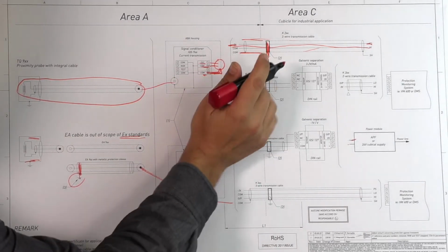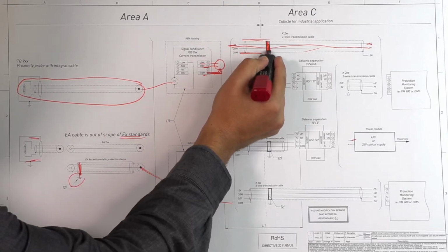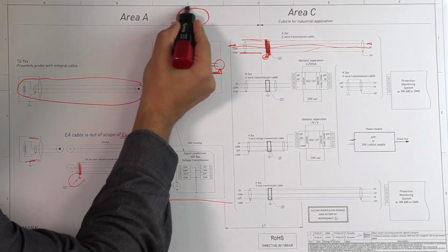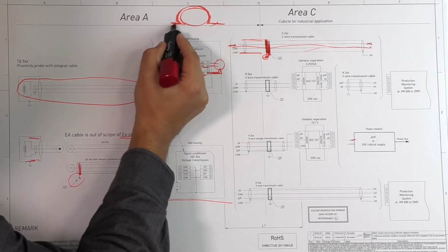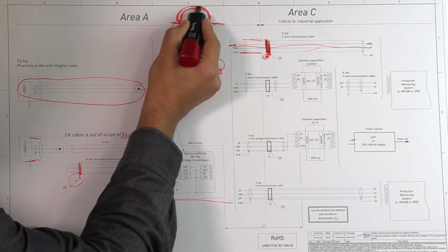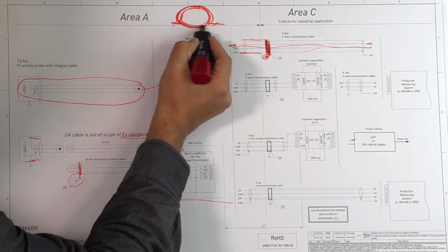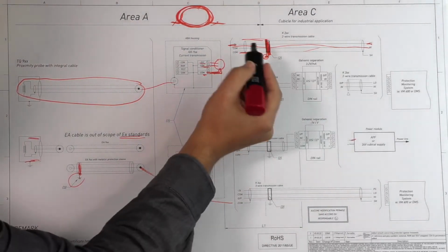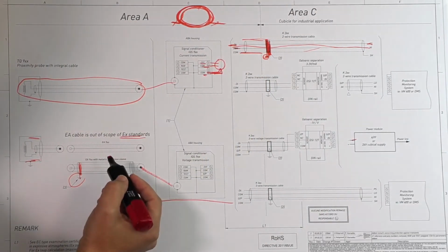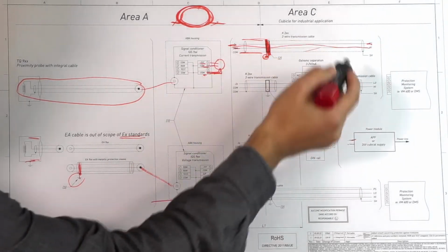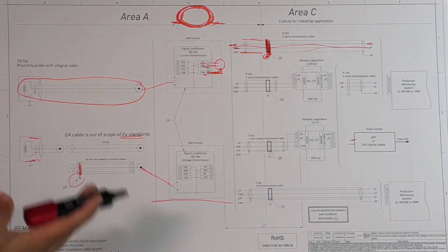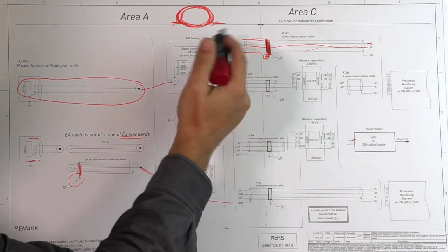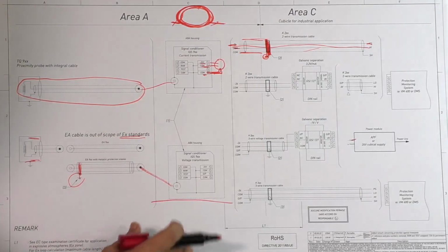And then the entrance of the cubicle is also very important, that the cable, so you have outer shielding of the cable, and this should be connected with a proper clamp to the ground. And this is to ensure that you minimize the impedance of this cable for mid and high frequencies, because this cable in the middle part of your transmission system will give you the reference to your system. So you will be concerned a lot more with low and mid frequencies.